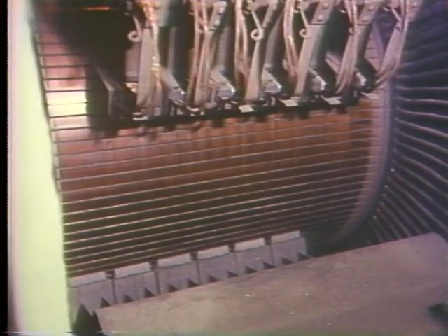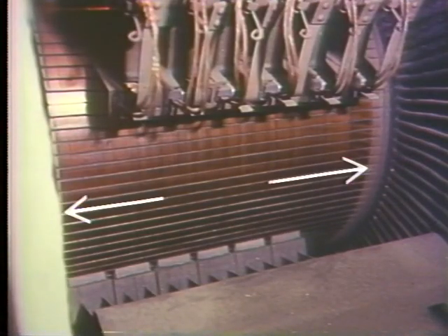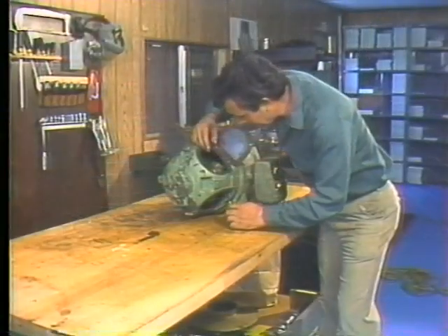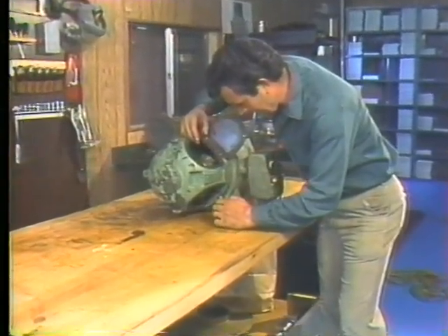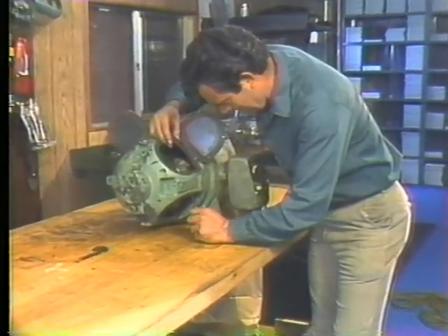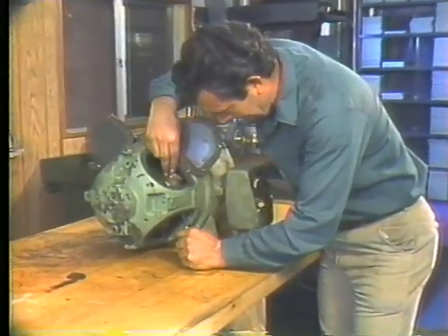The other thing you might have to do is adjust the stagger of the rigging so that the brushes cover almost the entire surface of the commutator. To do that, you loosen the brush holder bolts and move them so that the brushes cover as much area as possible. Make sure you always stagger the brushes in positive and negative pairs. Otherwise, negative brushes will track each other and wear unevenly.